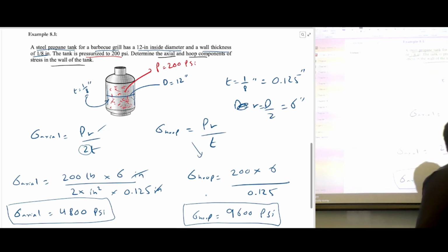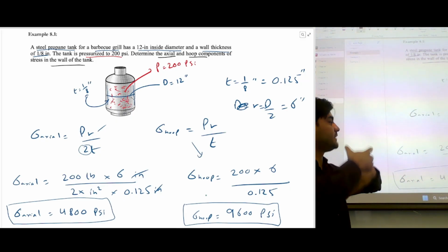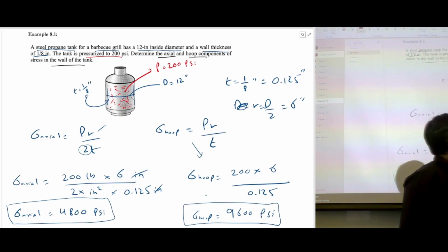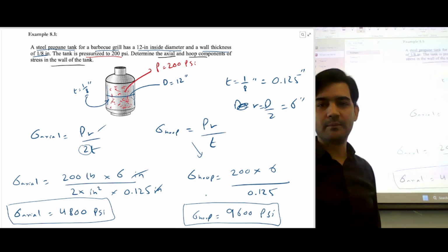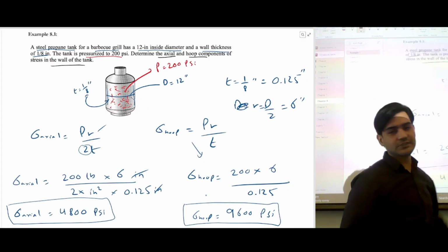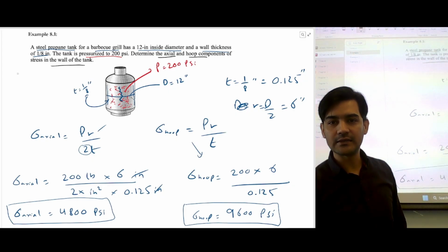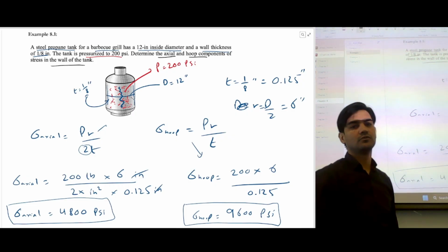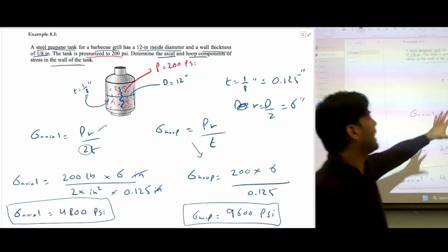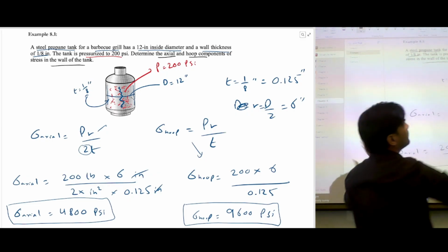So the stress along the circumference, which is the hoop stress, is twice, which is higher. So the failure is going to happen along the circumference. If you imagine, if you keep on increasing the pressure, both the stresses are going to keep on increasing, so it's going to fail in this direction. I mean, it's going to explode like this. So whenever failure happens in the propane tank, it's going to explode. You're going to see a crack in this direction, and that's how it's going to explode.